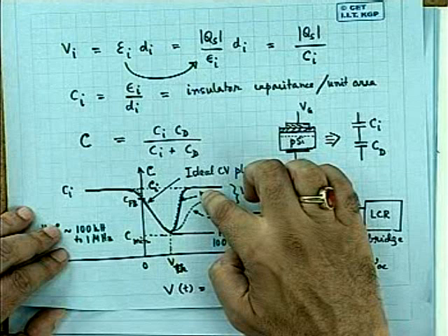And I told you, if you take that high frequency measurement, we expect that there will be something like this. The curve is otherwise the same as the initial portion. So therefore I put another green line over it, and this measurement we call high frequency CV measurement.